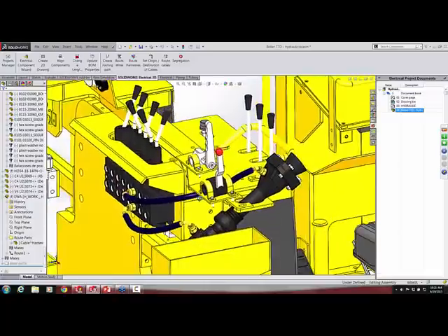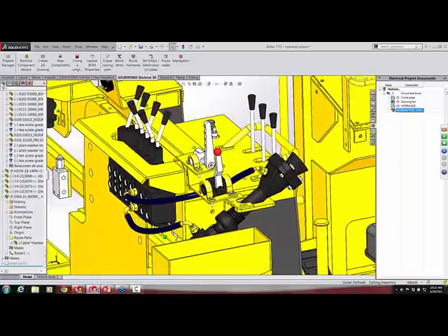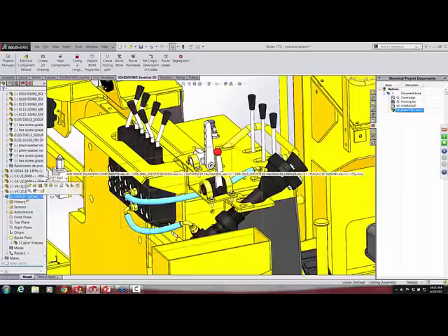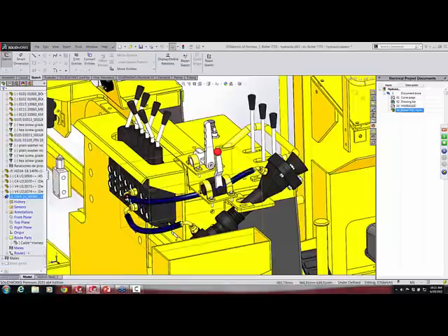And this would be good in a lot of cases, but if you need to make a drawing of the hose assembly, we can't really do it with this. What we need to do is actually make these hose assemblies, in effect, a harness. And then in a harness, we can flatten out the harness into a 2D drawing. So to show you that capability, I'm going to delete what I just did. Delete the two hoses that we created. Or actually, I didn't.